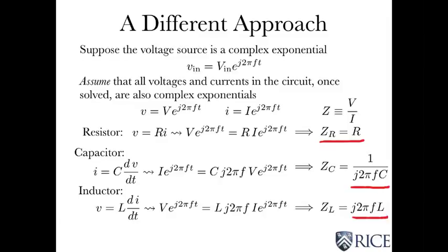So what this means is that we can think about every element in the circuit, resistors, capacitors, inductors, as being complex valued resistors, which is going to be the key thing. But we've now just checked the VI relations. We've got to check KVL and KCL before we figure out the consequences.